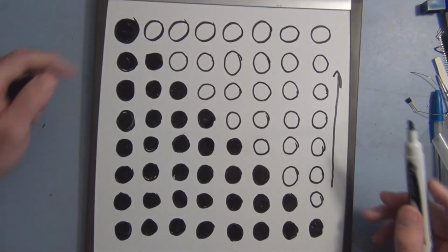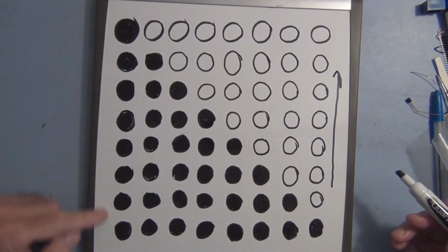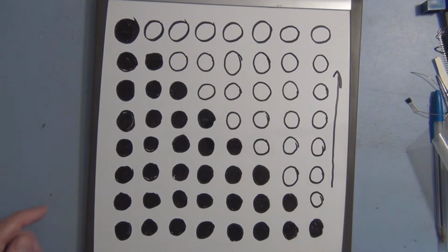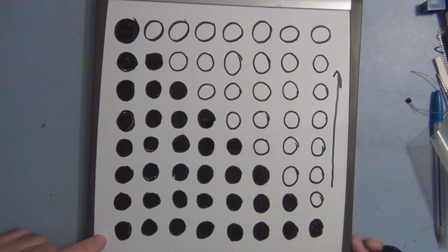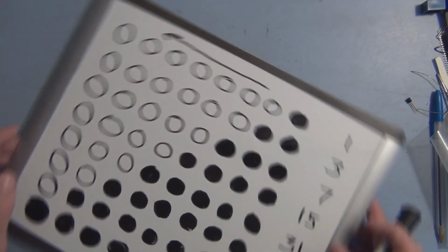Until the highest temperature, where we have all 8 LEDs turned on. So how do we do that? Well, we convert the degrees Celsius into a binary representation, and that binary, or 8 bits, gets shifted into the shift register to turn on the appropriate LEDs.